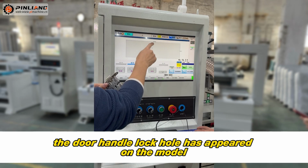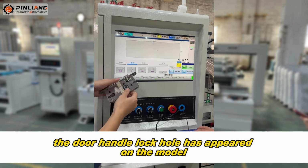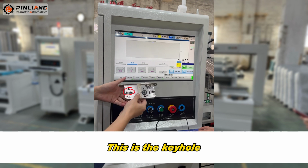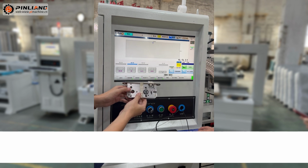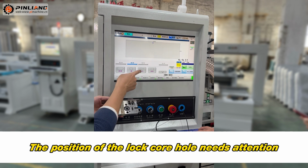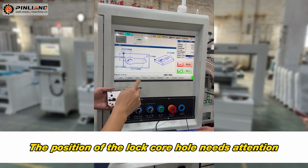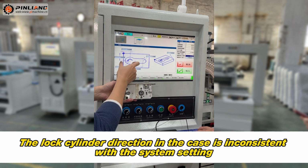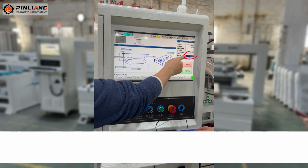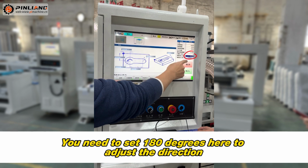The door handle lock hole has appeared on the model. Next, we will go to the setting of the keyhole. Select the keyhole to enter the setting. The position of the lock cylinder hole needs attention. The lock cylinder direction in the case is inconsistent with the system setting. You need to set 180 degrees here to adjust the direction.